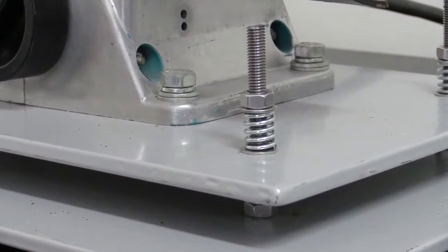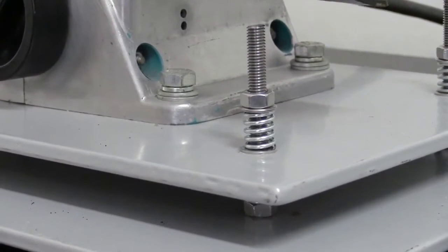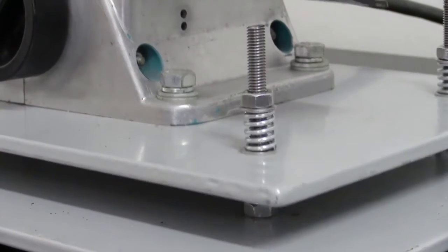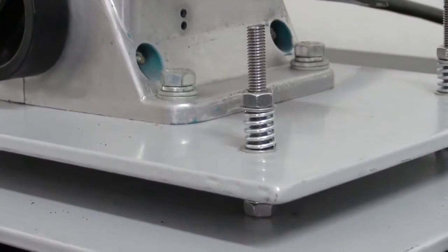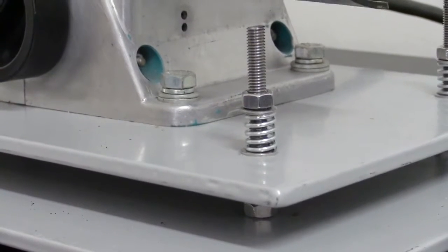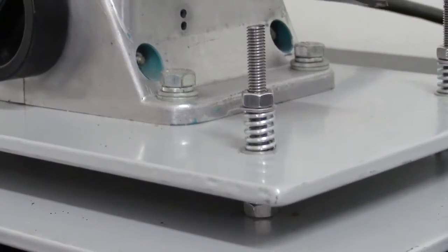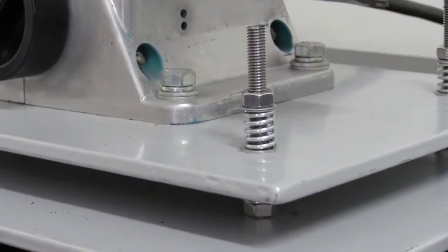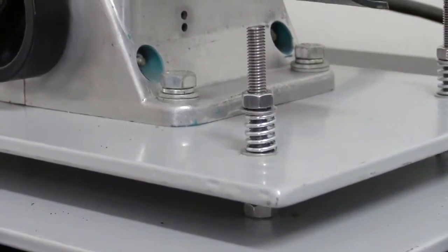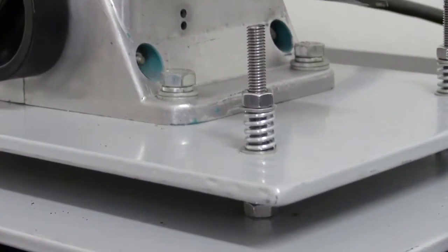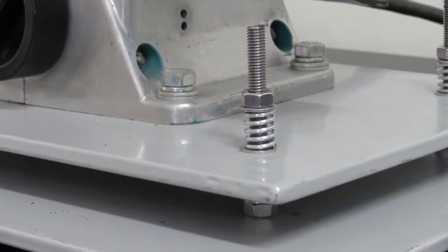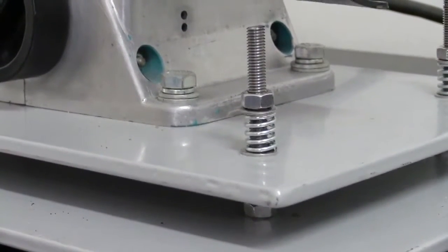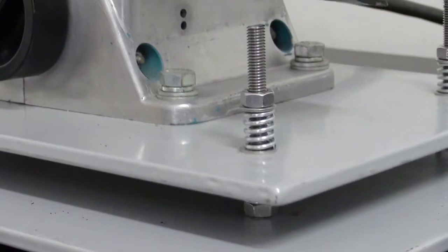You can see this demo rig, which does not vibrate too much. But I do a small change of the speed and you can see much higher vibrations. It is because of the situation when the speed is near the natural frequency. It is very dangerous to operate the machine near the natural frequency because small unbalance can generate extremely high vibrations. The machine can be destroyed very easily.